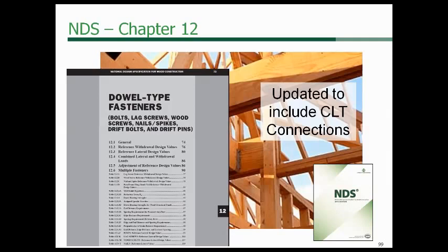When designing a lateral connection, you generally assume a uniform cross-section providing uniform bearing throughout the length of the fastener. But with CLT and the changing grain throughout the cross-section of the panel, you are not now having the uniform bearing along the length of the fastener. So we had to take into account that and a few other differences that are inherent with CLT versus solid sawn lumber or even glue-lam.